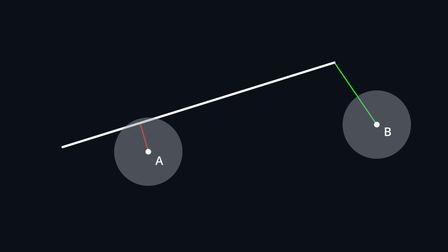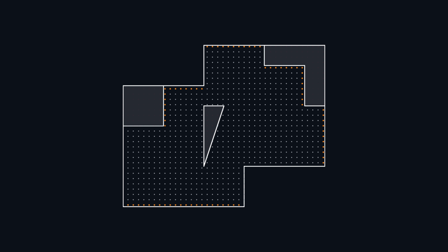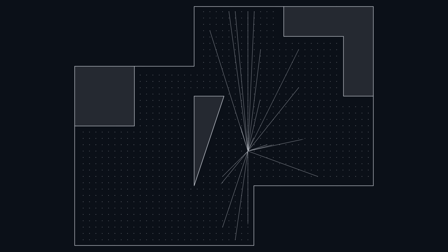It might help you to use a line that passes through the line segment. We have designed an algorithm like that, and we'll use it to remove all vertices that are dangerously close to any obstacles or the room's boundary. Now imagine the robot is at a specific vertex. Which other vertices can it reach by simply turning around and moving forward? There are quite a few such vertices.